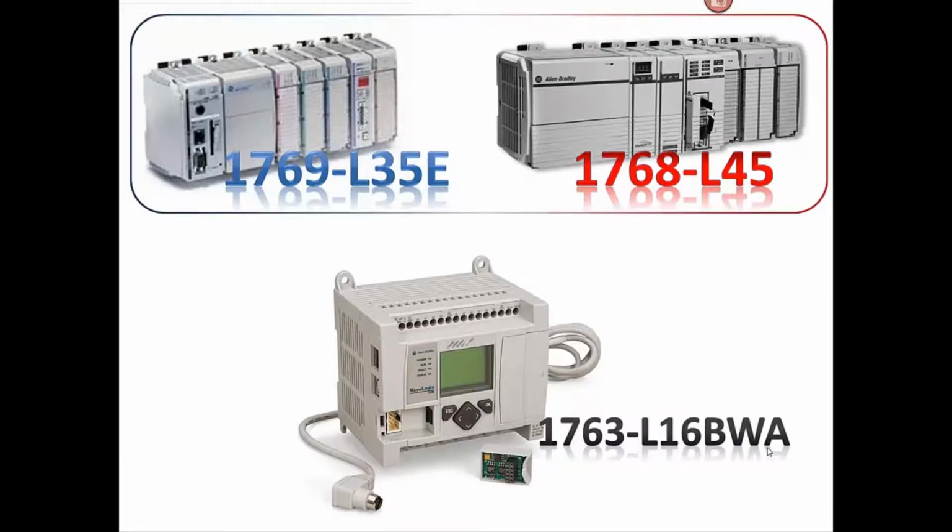Now in this case, we have two controllers from the same manufacturer, but really not totally the same family. The 1769 processors and 1768, they're both CompactLogix, but they're two different platforms. Because they are both the Logix engine, the communications are inherent in every design consideration, and as a result are native to both hardware adapters, memory data structures, protocols, and of course the icing on the cake, as they say, is the integration into the programming platform, which in this case is RSLogix 5000.